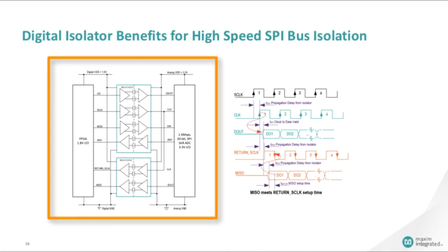In low-speed SPI communication, the master clock would also be used to clock data traveling in the reverse direction. However, in order to compensate for the fact that the master clock has already been delayed by the isolation in the forward direction, it is better to return a copy of the isolated SCLK, shown here as CLK, when clocking data in the reverse direction from the ADC to the FPGA.